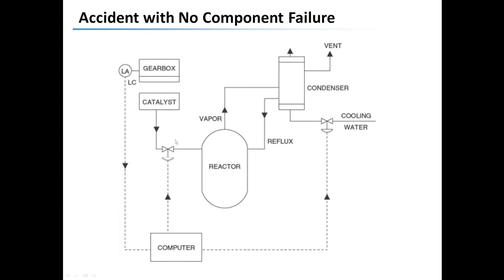There are multiple solutions on any of these problems when you have interaction accidents, but one solution would have been to tell the computer software engineers, always open the cooling water valve before you open the catalyst valve. But nobody thought of that. The engineers may have thought it was pretty obvious, actually. They've told me, well, of course, every chemical engineer knows that. And I say, well, these software engineers weren't chemical engineers.